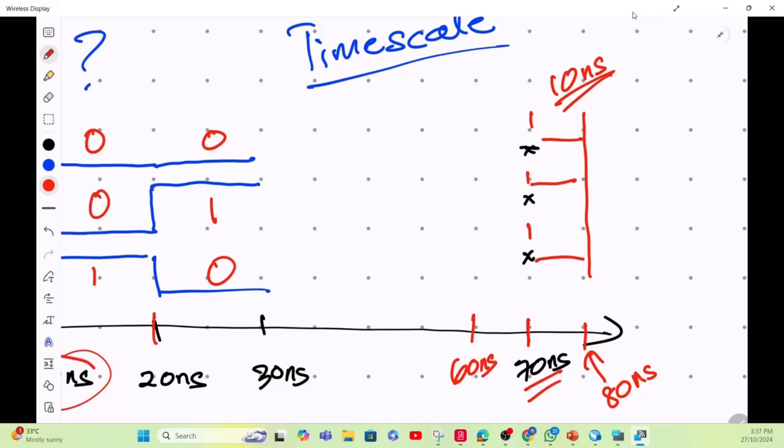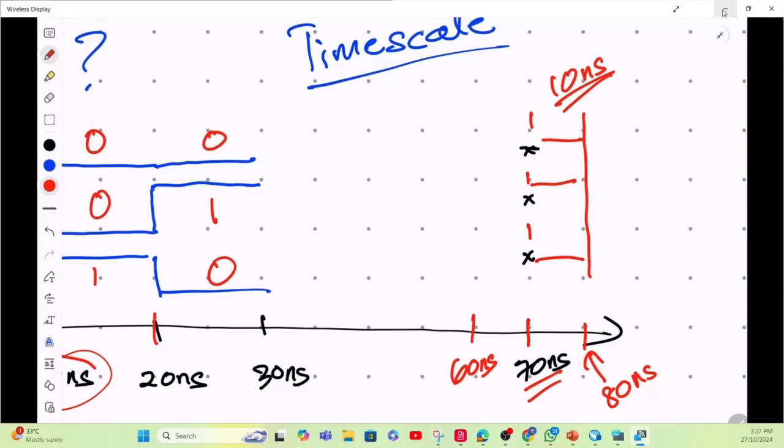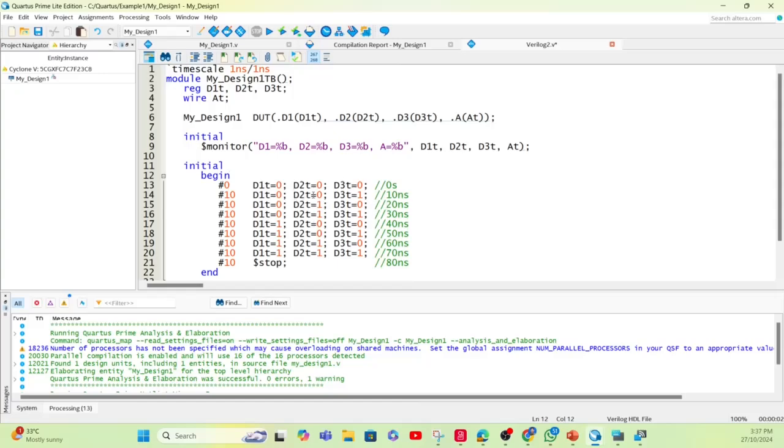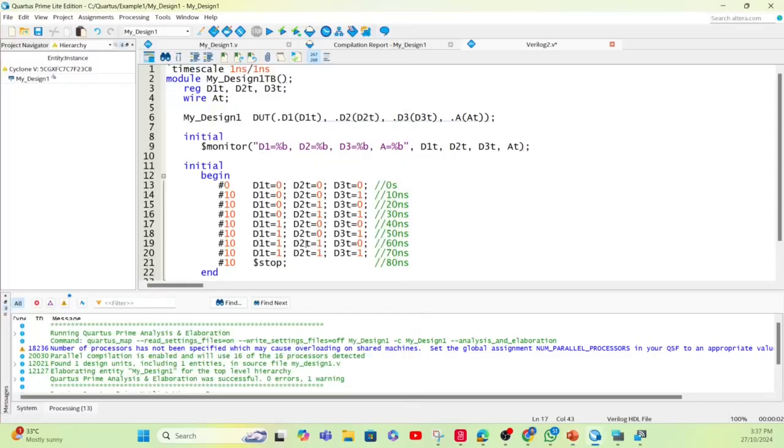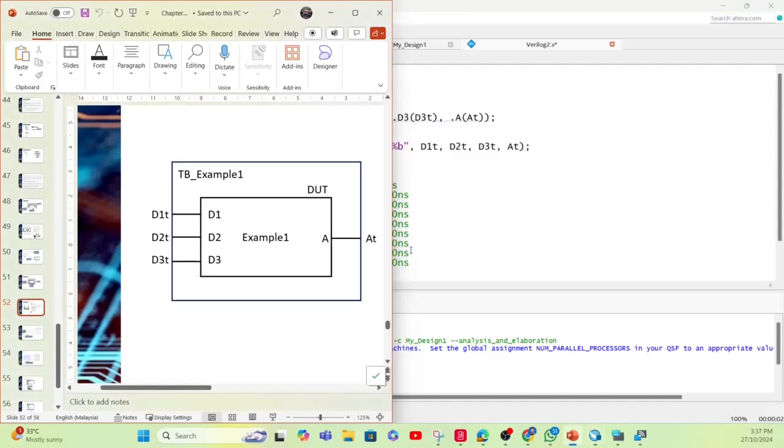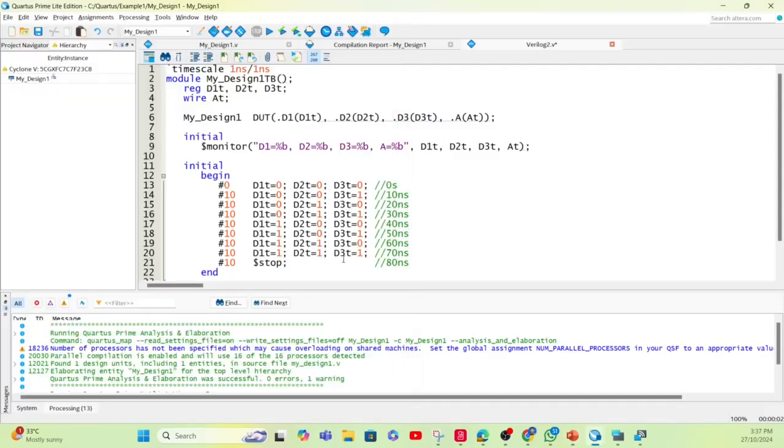All right. We will see in detail in other example, for example. So in this case, in this example, the input is 000 to 001 until we have 111, because our design we have only three inputs, so it's easy. If you have 4 inputs, so you need to have up to 16 input combinations, right?